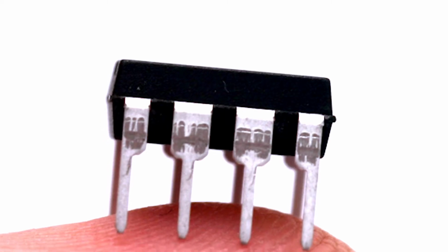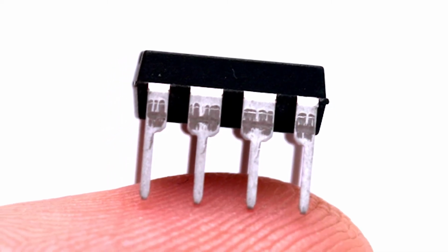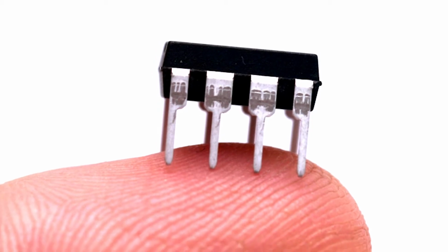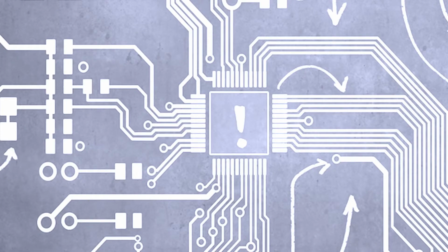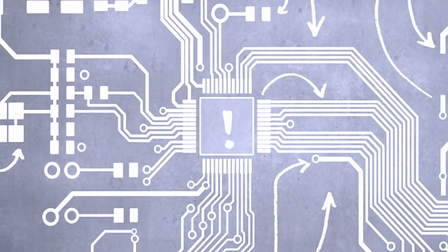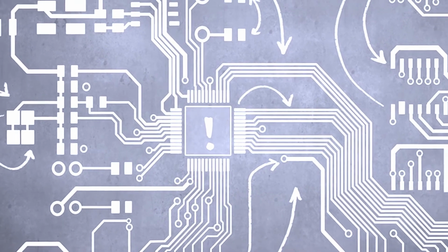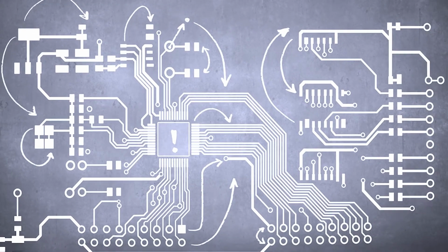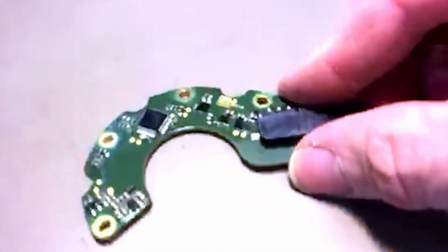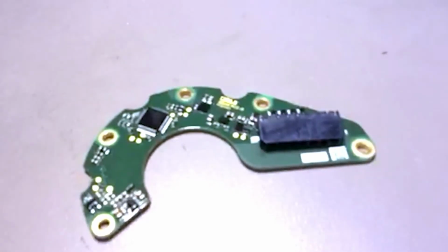Being open source, schematics for Arduino boards and outboard components are available online to download and modify. This allows you to shrink your microcontroller and other electronics to only those components required for your product. From there, lay out your PCB components, add a locking connector for your outboard connections, and send your layout file to a board manufacturer to make and load. The result is a solid circuit board ready for validation testing.